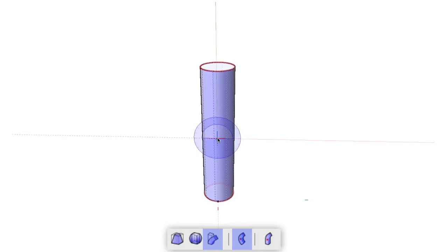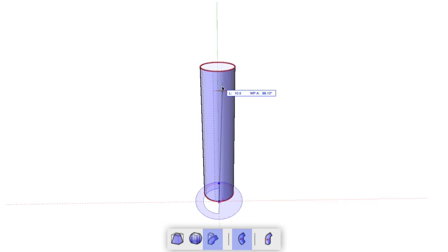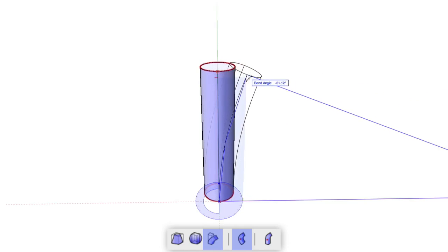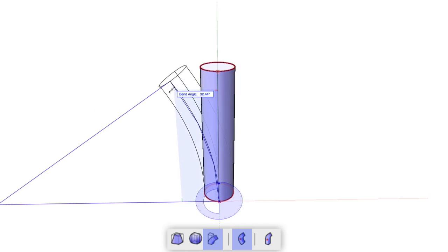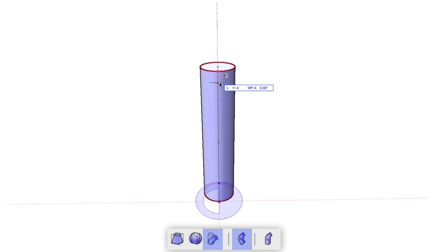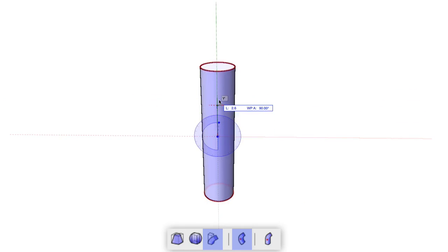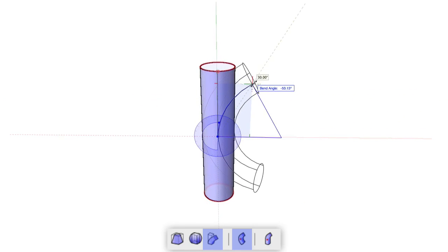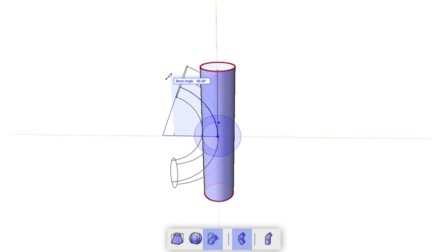As with the other modes, first select the object. Then, the next click will determine the point where the object will be bent. If you place this modifier at one end or another of a straight object, that end will remain where it is and the other end will be bent. If you place this modifier in the center of the object, the two ends will be bent and the middle will remain in the same location in Symmetric mode.